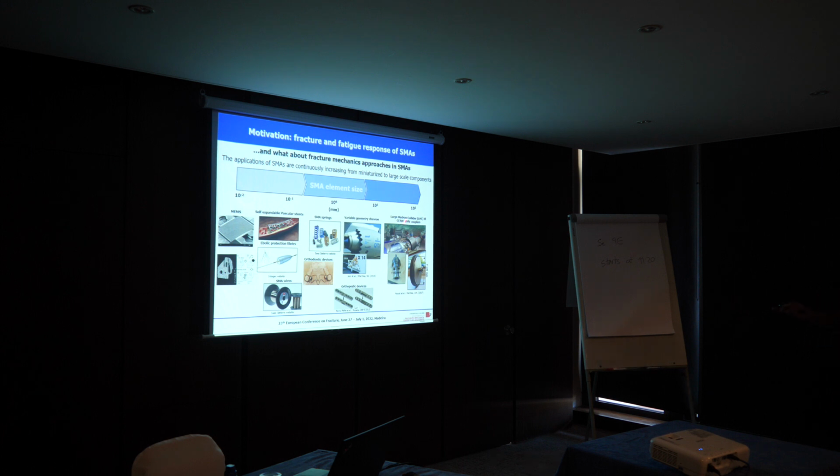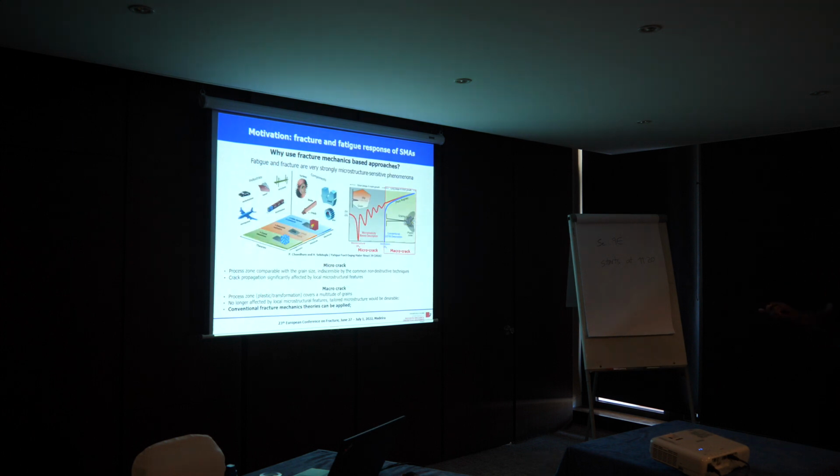I would like to mention one of them. This is a project in cooperation with the European Organization for Nuclear Research in Geneva and my research group that is about the development of bulk NiTi couplers, pipe couplers with very interesting sealing capabilities, to be used for coupling the beam pipe of the particle accelerator at CERN.